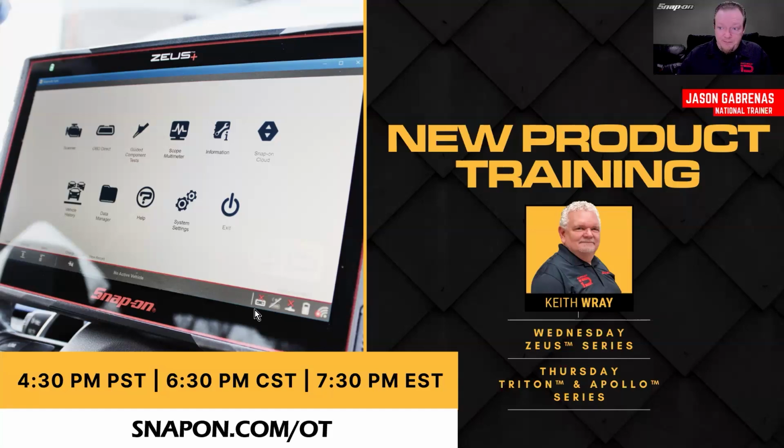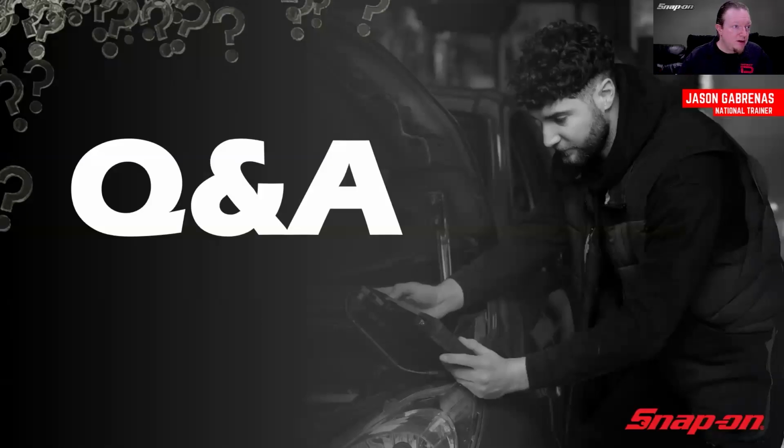All right, let's see. So I have questions. Here's a good one from Antonio. He said: 2019 Jeep Wrangler, communication issues with ABS module, typical issue, star connector. Those multi-joint connectors I showed you on the Subaru also exist on many other manufacturers, so it ends up being the star connector. And he said scope helps watching the glitch when driven. It's not always the module. You're right, not always the module. Sometimes it's a bad ground, like we saw in the case study. Sometimes it's the star connector. Something goes wrong in there. Excellent information. Thank you very much for that.